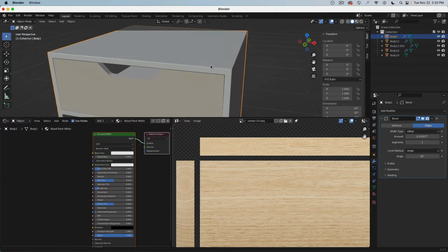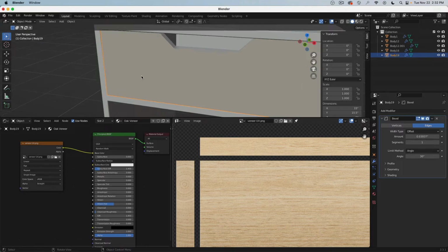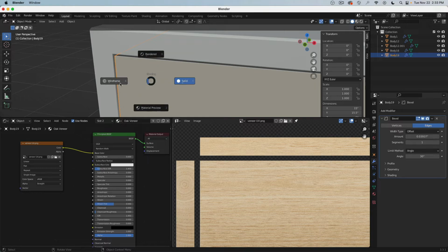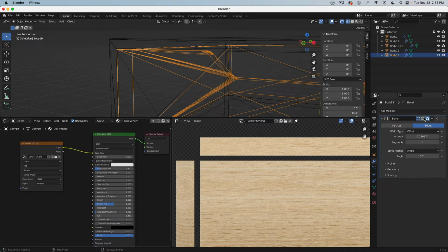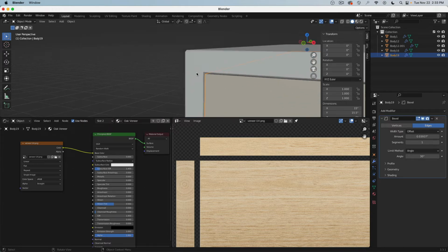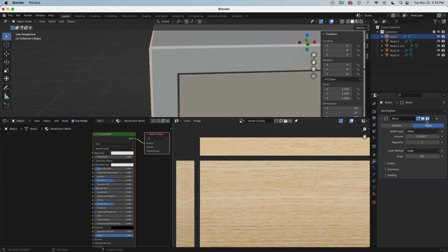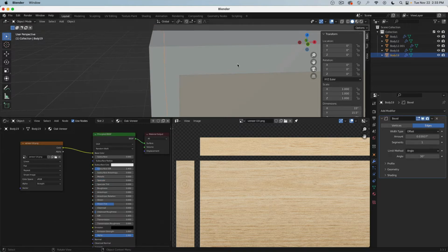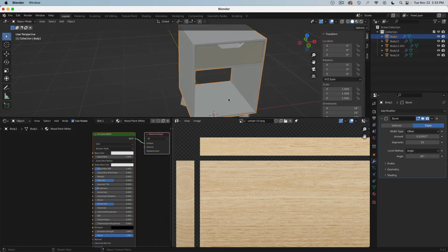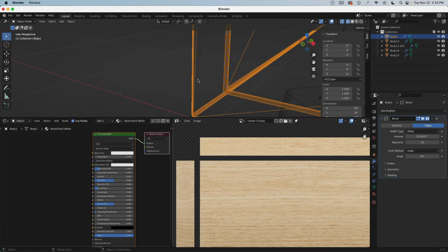It's kind of like breaking this edge. And select this. Also here, bevel 1 millimeter. Zoom in. How does this work? Z and wireframe. Yeah, you can see there's a really tiny line. Okay. So this is like a super quick fix to issue this. So if we turn this off, now we can see something's kind of missing. We can also make this 10, then actually more is being rounded. This is also a very basic geometry, so this effect actually will work really well.